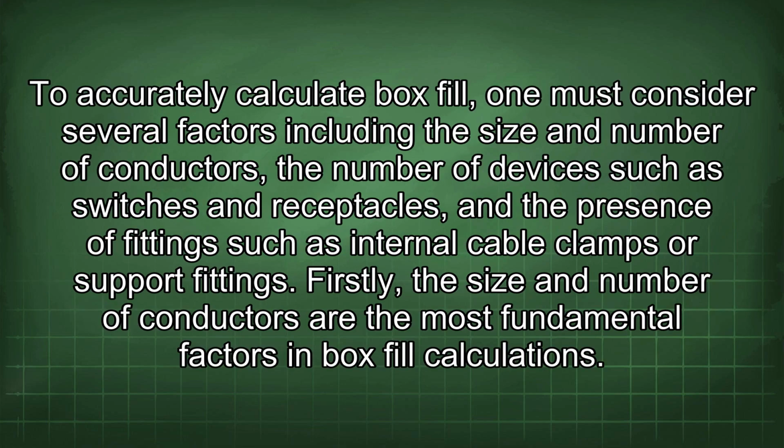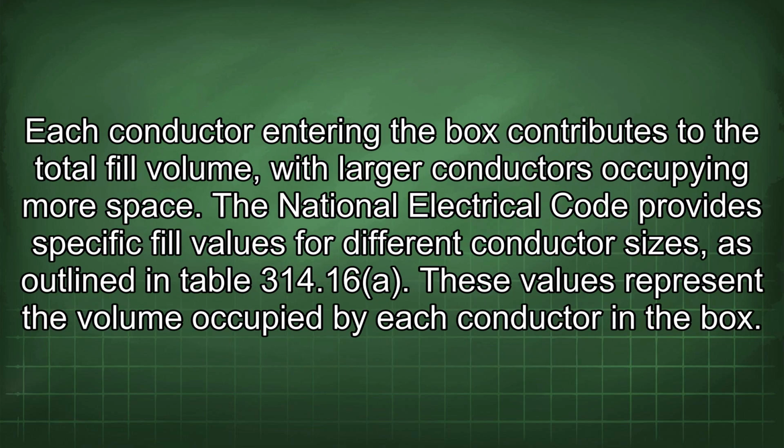To accurately calculate box fill, one must consider several factors including the size and number of conductors, the number of devices such as switches and receptacles, and the presence of fittings such as internal cable clamps or support fittings. Firstly, the size and number of conductors are the most fundamental factors in box fill calculations. Each conductor entering the box contributes to the total fill volume, with larger conductors occupying more space.